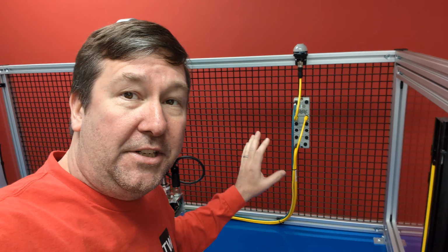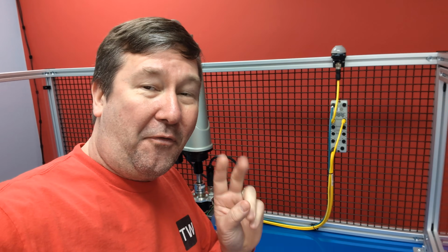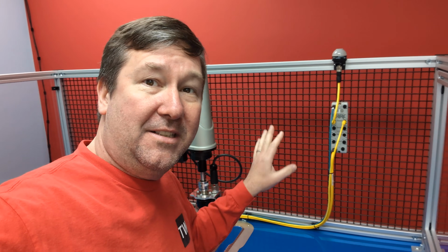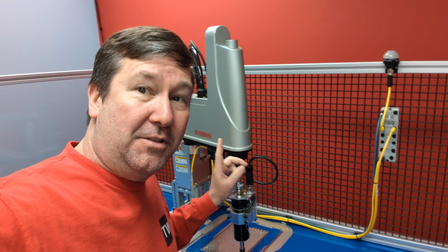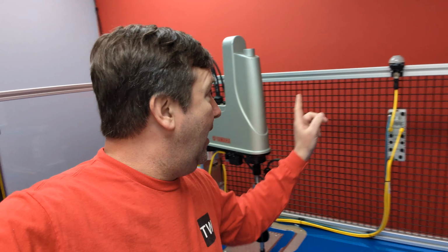We have our 5032 IO-Link module from Rockwell Automation mounted, and we have our first two devices connected to it. I thought this was a good time to stop and talk about how we're going to configure this in Studio 5000, mainly because we have an Allen-Bradley distance sensor and a third-party Banner IO-Link stack light, and that really shows some of the cool advantage of this 5032.